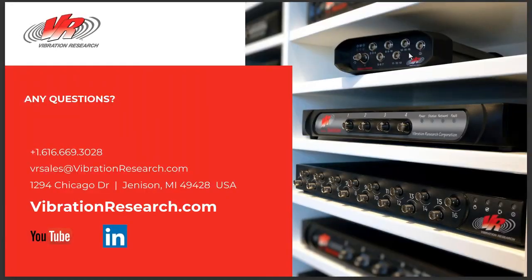So we conclude this webinar by summing up what we discussed. We introduced a key component of random vibration testing, the PSD. We talked about a brief introduction into random. We talked about some key terms. We stepped through how the power spectral density is calculated and the meanings of the words power, spectral and density. Finally, we reviewed windowing, overlapping, degrees of freedom, and lines of resolution.